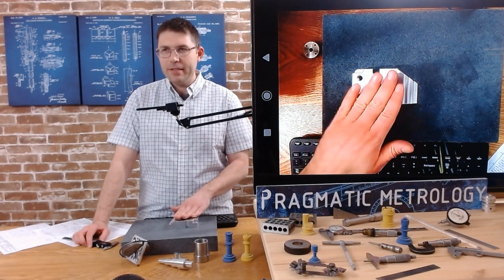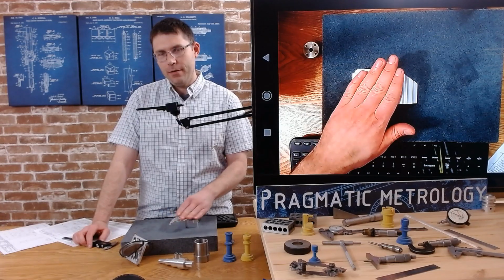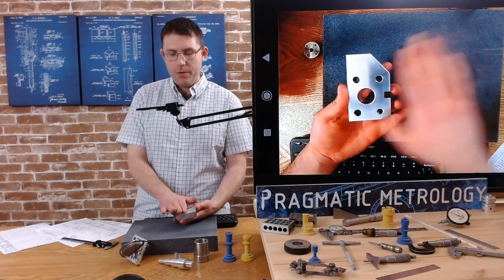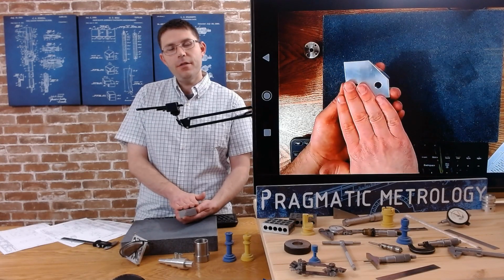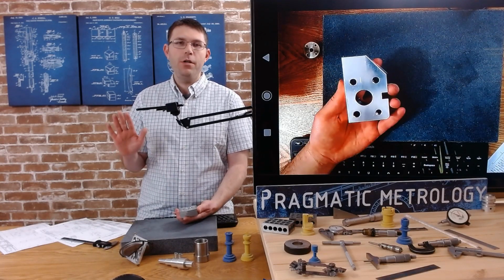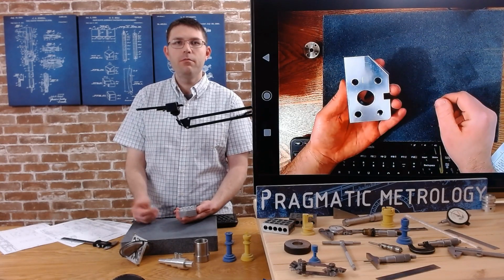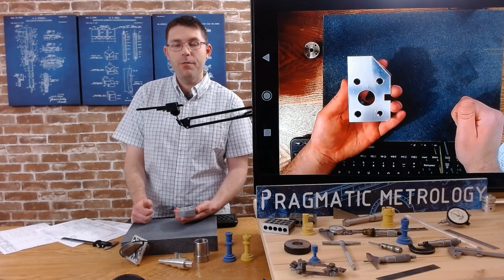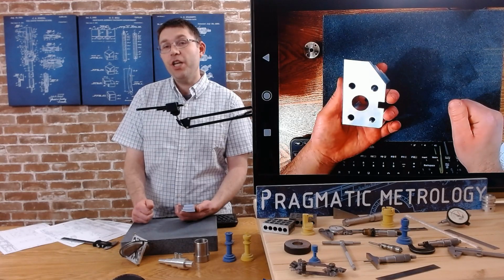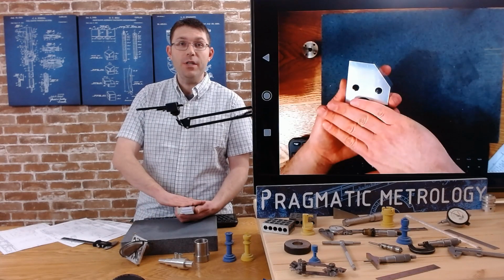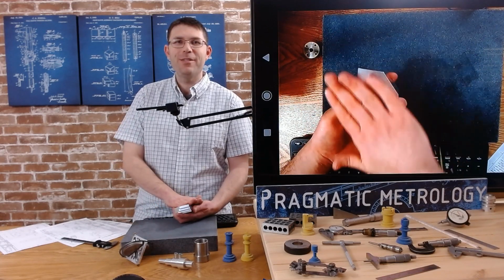Why isn't this datum A? Is there a reason the back is datum A? Talk to your engineer, is there a functional reason this is datum A? If there is, hey, leave it alone, right? The designer picked a good datum for the final form of the product. Maybe manufacturing should change their operations and do this first, but hey, I'm not going to be the one to say that. I'm just the inspector.